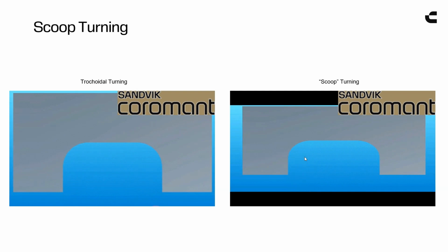That's another fantastic solution for deep pockets where you may have a really long reach blade attached, and you don't want to go down in the pocket and then drag the insert back up because it puts too much flex and bend moment on the blade. So in certain particular situations, or even for thin walls like seal fins, scoop turning might be the way to go. So just another technique similar to trochoidal turning. And going beyond that, as I mentioned, a lot of the CAM softwares are rolling out their own version of this, like volute turn or dynamic turning, that incorporates this technique.